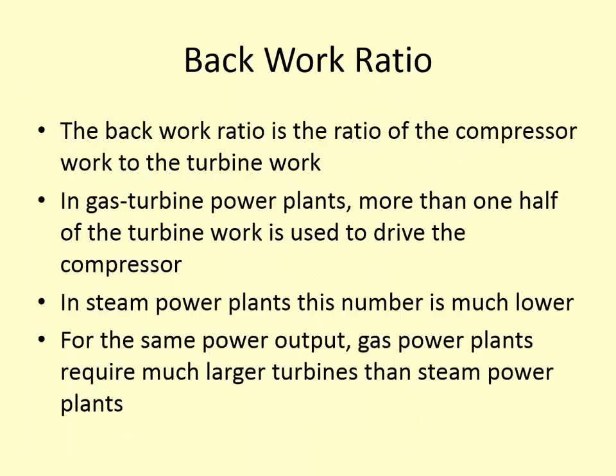So the back work ratio is the ratio of the compressor work to the turbine work. Some of the work from the gas turbine is used to actually power the compressor. And in many cases, more than 1/2 of the turbine work is used to drive the compressor. So in steam power plants, the fraction was significantly smaller. And do you remember why that difference is? So in steam power plants, are we using compressors or what are we using?